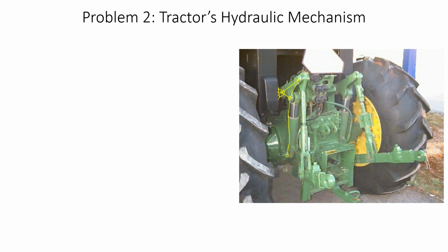One thing that is different in this particular link is that you can obviously see a hydraulic actuator over here, which means that this link has got extendability in it, so it is a prismatic joint, to be precise. Now over here you can see the lower node down here is also a ground node, which means that these two nodes can be considered as part of the ground link.